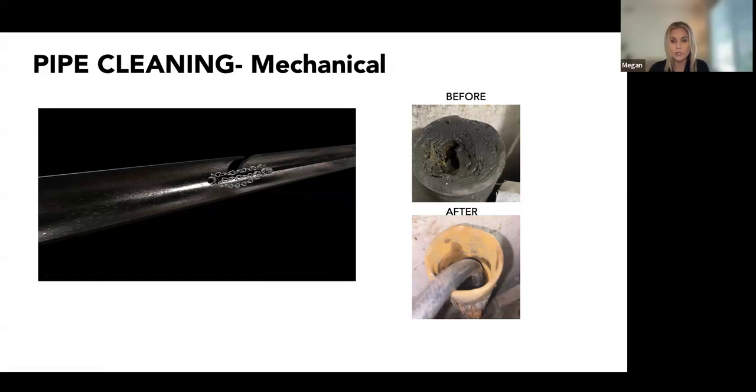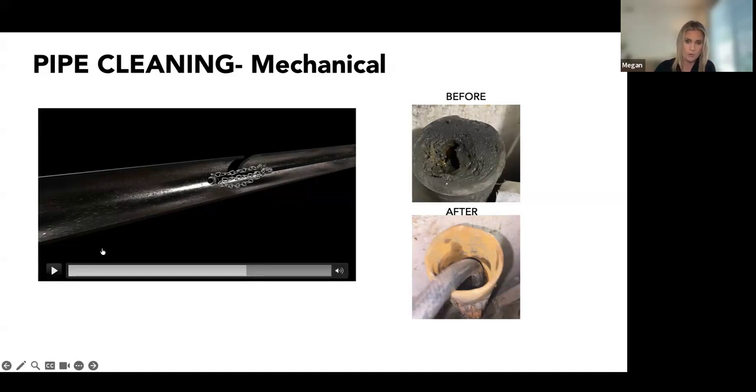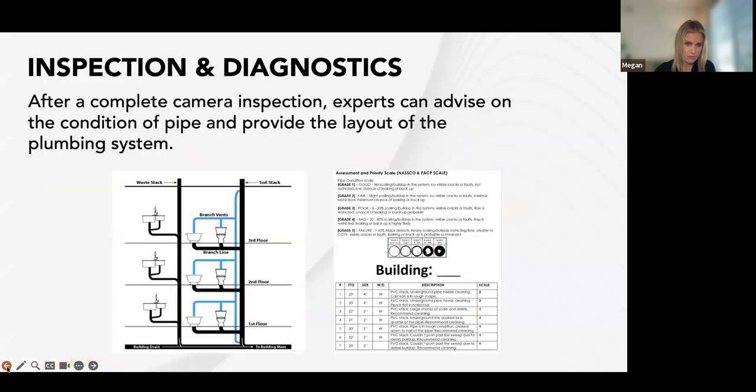Yeah, so basically what we do is we'll go into your plumbing system, either with the vent, and actually I'm going to go back a couple slides. So right here, we can enter the vertical stacks, which are these right here, through a vent. If we have roof access, another point of entry would be removing toilets, or if there are exterior cleanouts on the outside of the property, and also manholes within the site sewer. So a couple ways to get into those pipes. If you don't have access, we can locate where the pipes run and actually create access.